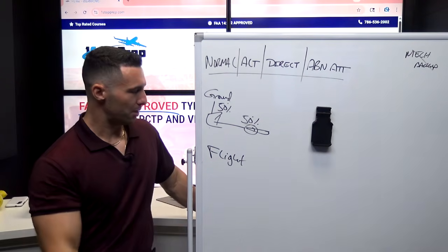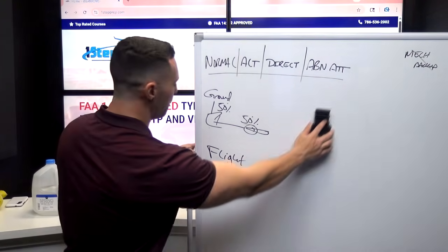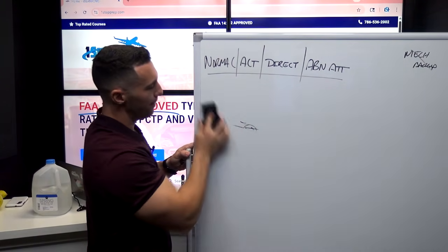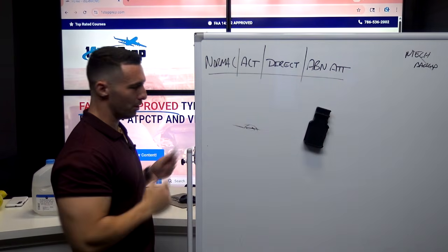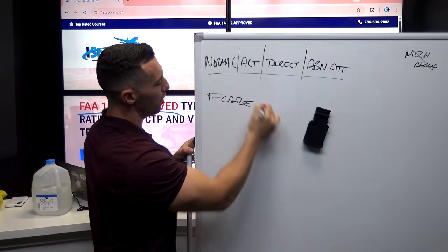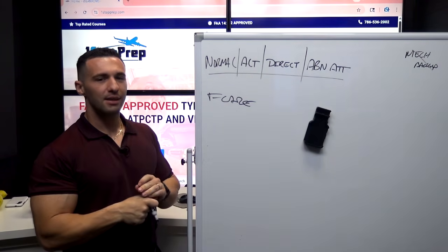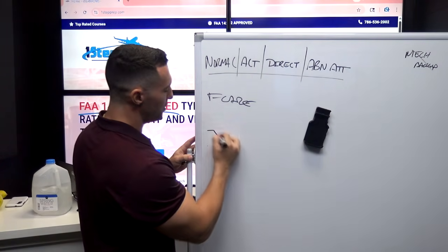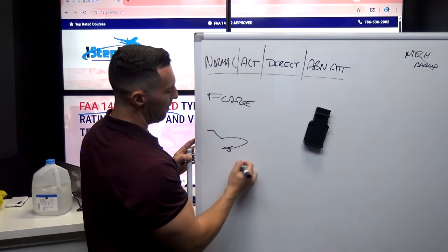So just something to be mindful of. The last thing I'll share with you is that we have flare mode. We got flare mode, and flare mode, if you don't know, is only available in normal law. Basically, the ELAC takes a snapshot of your pitch attitude on the approach, and this is going to happen right